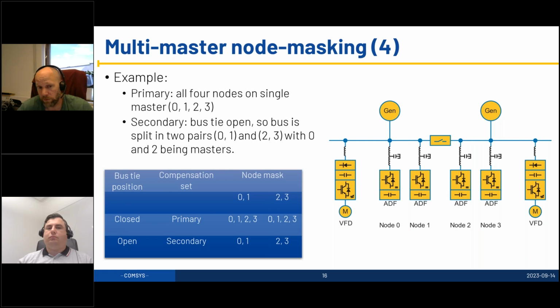Now we're adding capacitance to the grid, and maybe now on the 17th harmonic, the impedance is further a factor of 10 times increased, meaning that maybe we have 170 times more impedance on the 17th than we had on the fundamental. And this is what we want to work with impedance control in the ADF. We want to lower this 170 to something more nice, maybe 20 or 10 or 5 or something. But we will still have much more impedance than we have on the grid.